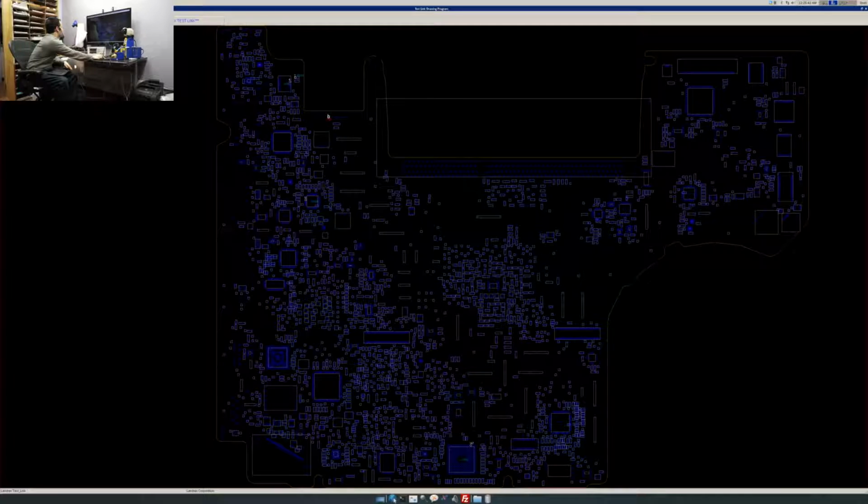So here we go. So that's the pull-up resistor, R5280, and you can't see my mouse, so I can't really narrate well. Then in the upper left corner, you have the battery indicator. It goes to the battery indicator. Obviously, the battery indicator, in order to know what the battery is doing, should be attached to the data line that's going to the battery. You have it going to the battery charger chip, the U7000, a little bit lower than that, and then below and to the right, you have it going to the third upper right ball on the SMC, which is U4900.